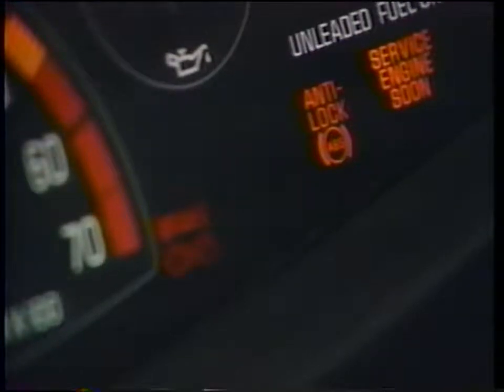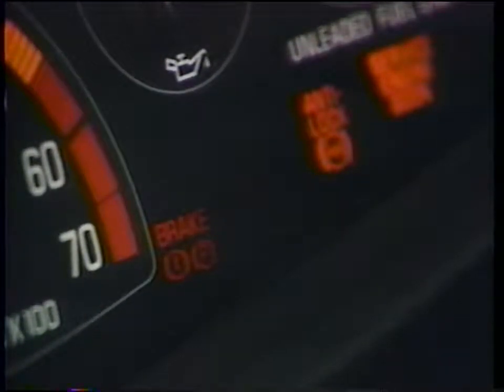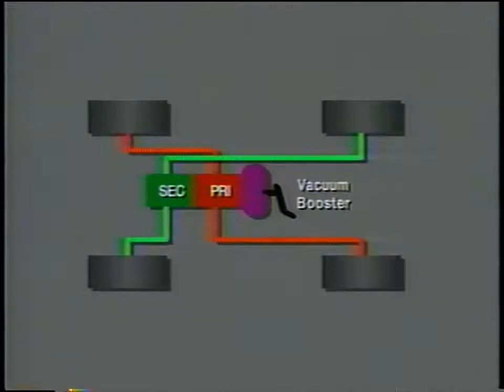The other lamp is a red brake light that comes on when the parking brake is applied or if the hydraulic pressure has been lost in either the primary or secondary side of the brake system. The master cylinder is a compact tandem design with a vacuum power booster.